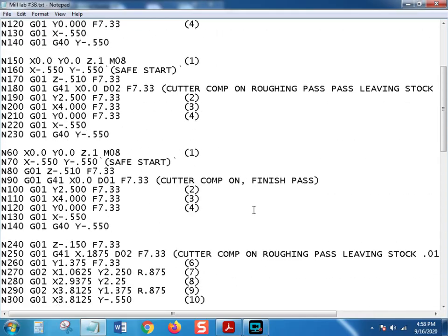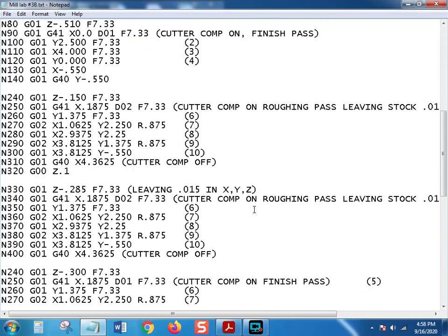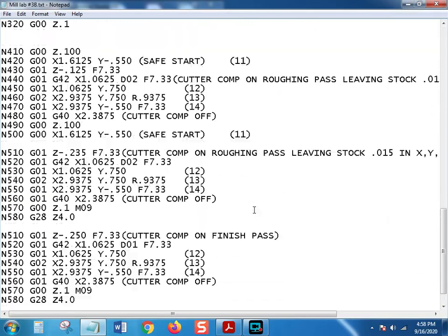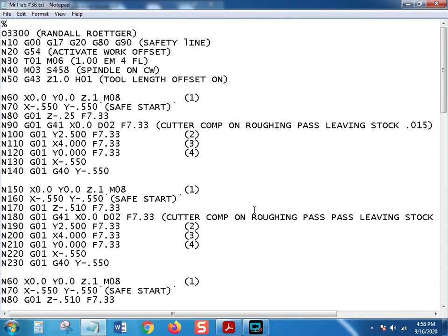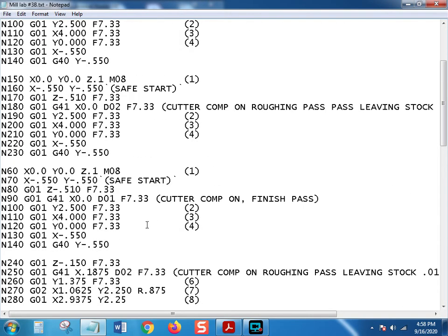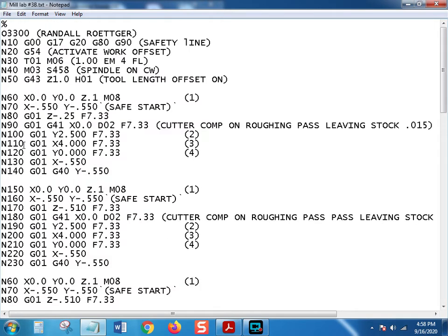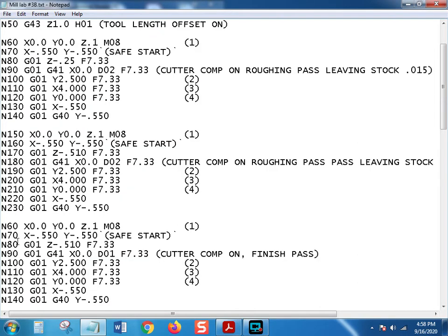Now it does look like a lot of lines, and it is. We've been working on it. Now you're going, well, none of the lines are sequenced, so I'm going to show you how to resequence them. Again, you could do it manually, like, oh, we could go up here and go right here at this point all the way to 230. It's fine. Then I go in 240, 250, 260, 270. All right, that's fine, but there's automatic ways to do that.